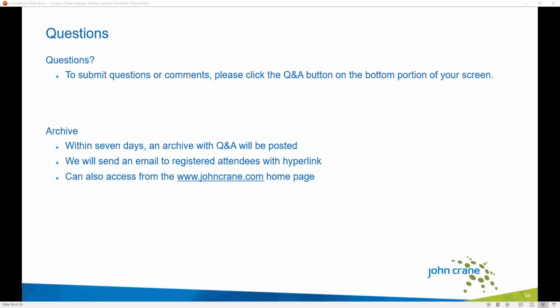Sure. So this question is quite common: how much leakage is the right amount, or is too much? At risk of giving a dissatisfying answer, the answer really is that it greatly depends. Mechanical seals are extremely sensitive to very small changes, which can have a significant impact on leakage. What I can say is that for many mechanical seals, about 90% of them out there in the field working in general industry, you're looking at measuring the leakage in a few grams per hour.